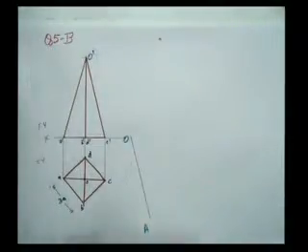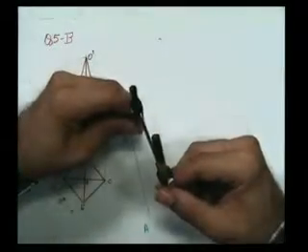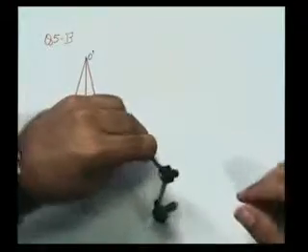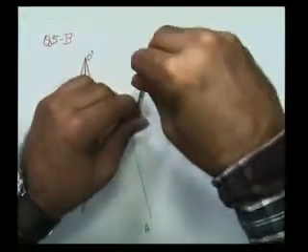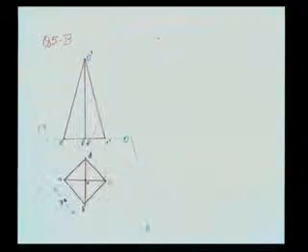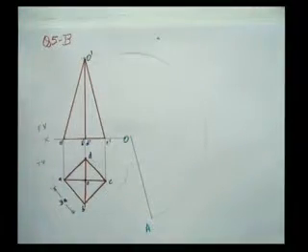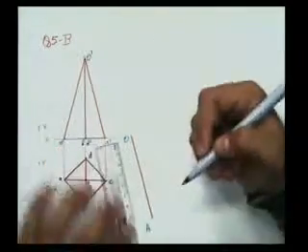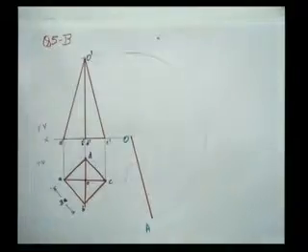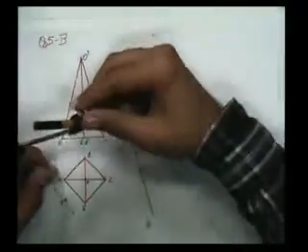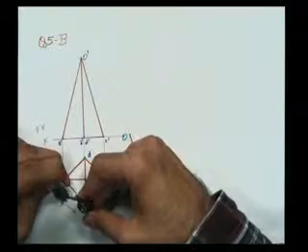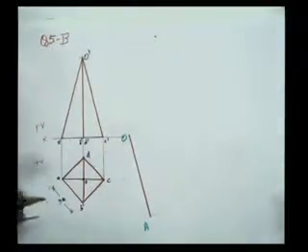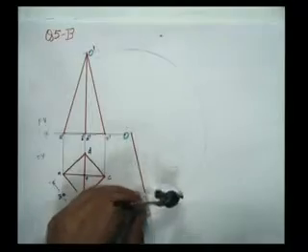Now what I need to do is again the same radius, putting it at the center, the radius equal to same. I'll draw a simple curve. Now after doing this, I need to find out what sides are there. So this is one of the edges that I have already obtained. Now I need to obtain all the other edges which form the development of the pyramid. So for that, I'll take the distance AB, that is equal to 3 centimeters, and I will cut successive arcs on this.